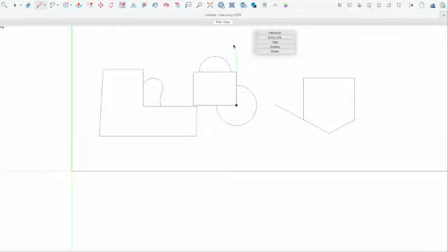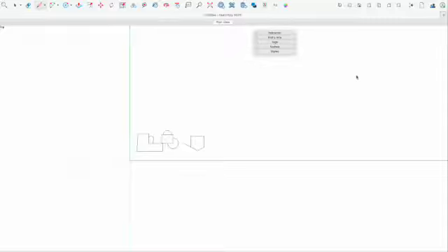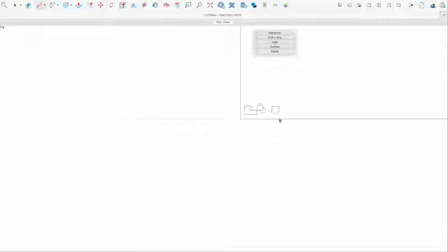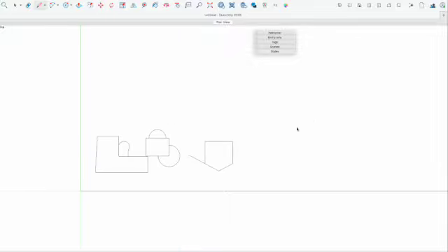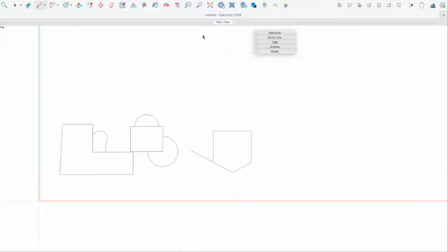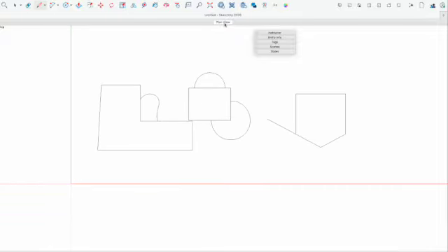One last thing, you can easily zoom in or out of your drawing. Just use your scroll wheel on your mouse. You will find that the drawing or model moves in different directions depending on where you have your pointer. It's really easy to get really zoomed in or out, and at first it will seem tricky to get back to your starting point, but really your starting space is saved in your Plan View Scene tab at the top of your drawing space. Just click it and it will reset back to your original view. Your Plan View tab in your template is set to be the top-down view, and to keep the origin, which is the intersection of your axes, close.